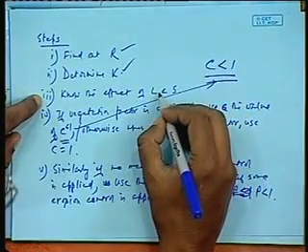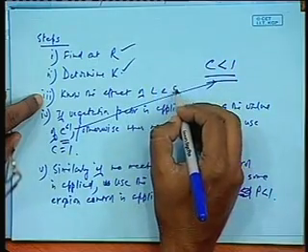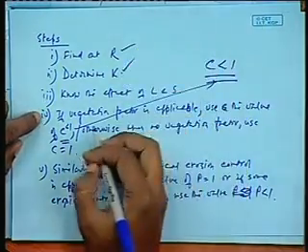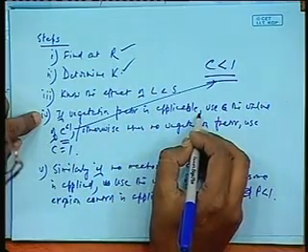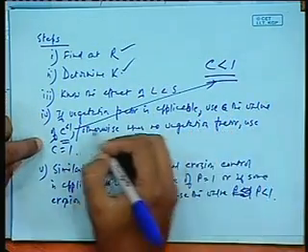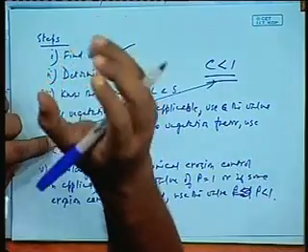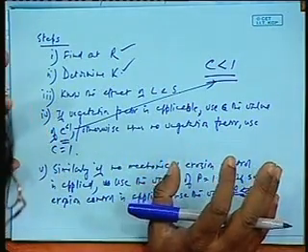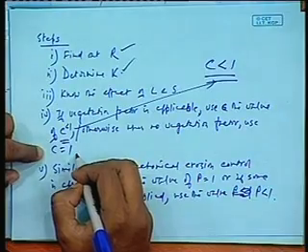Know the effect of L and S. Length and slope should be known. Generally, as a parameter it is given. If the vegetation factor is applicable, use the value of C less than 1. If any kind of vegetative factor is used, that means some form of haze, some kind of mulches have been used, then we will say that C would be less than 1. Otherwise, when no vegetation factor is used, use C is equal to 1.